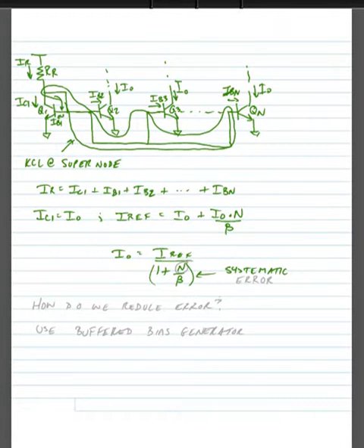In other words, we'd like our output current to equal our reference current, but because of the finite beta of the transistors, it doesn't. And of course, this is worse than the prior expression that we looked at for a bipolar transistor, because as we increase the number of transistors that we're biasing, we get this increase in the size of the denominator, and of course our error increases.